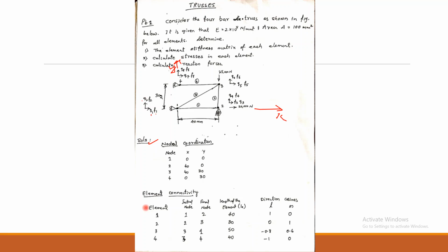As usual we have around 5 to 6 columns. In addition to that, I will suggest adding Young's modulus E, and cross-sectional area A, as well as one more parameter that I picked from the previous one, which is global connectivity. So you will remember global connectivity. Let's go for each element and define the position, nodal length, and direction cosines.